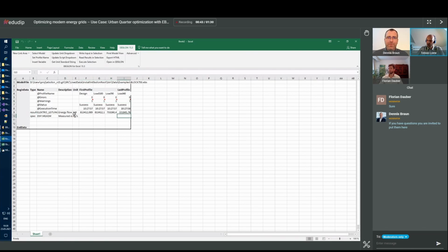Now I can override more or less the load of the model, because I know at full load it has roughly 600 kilograms per second. But if I specify 500 here, I should get a higher produced generator power, now at almost 700 megawatts. And you can have arbitrary large Excel sheets, and people do that.